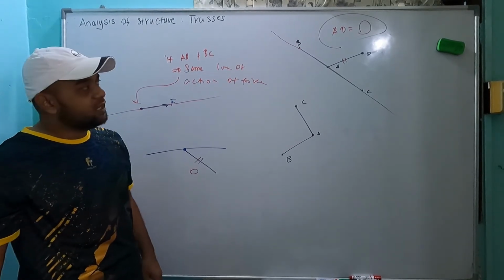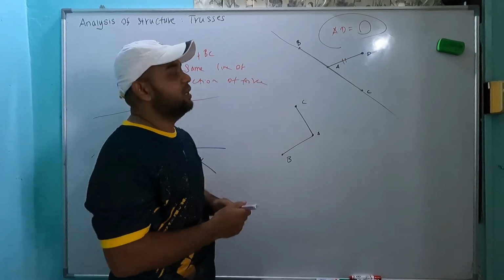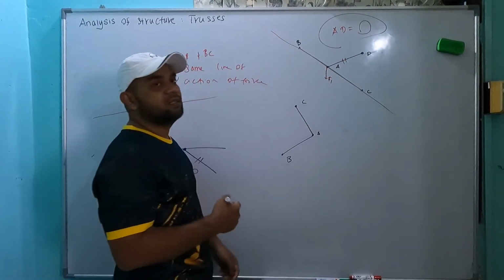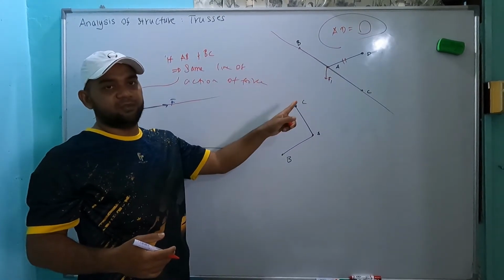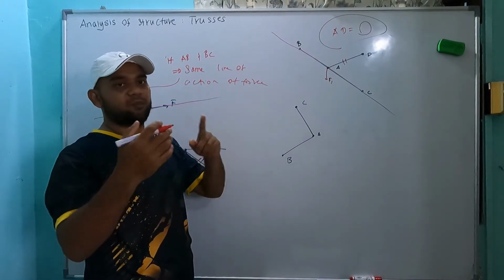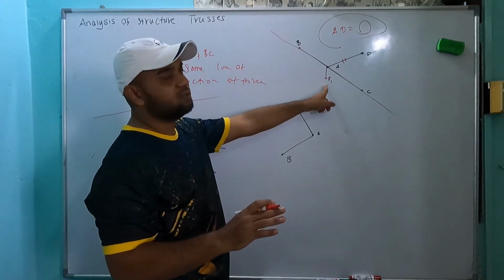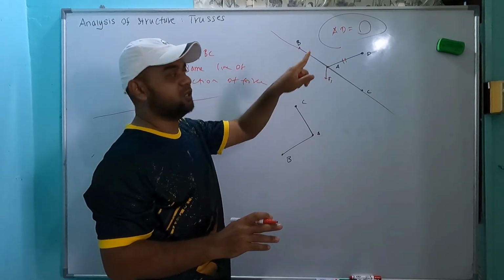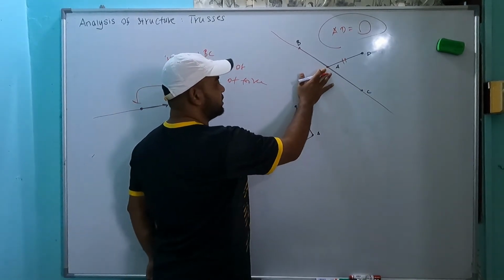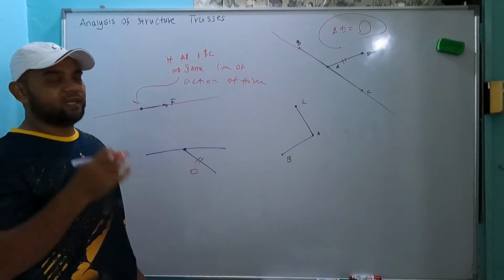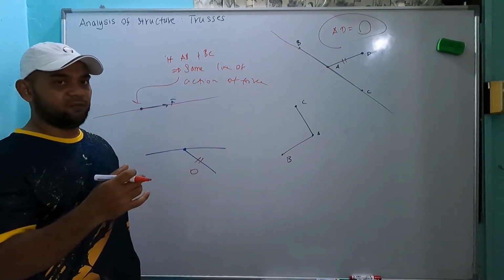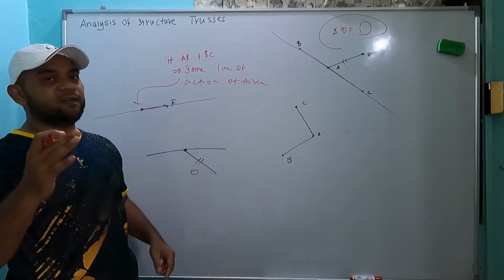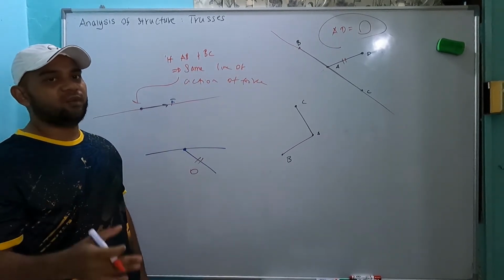But if we have three components and there is already another force F1, this rule cannot be used because there is another force pushing or pulling. This consideration cannot be used because there is another component, another force that is pushing. But we are talking here about only three forces. Three components meaning three forces, because we know it is a two force member. So three components, two in line, the third one must always be 0.